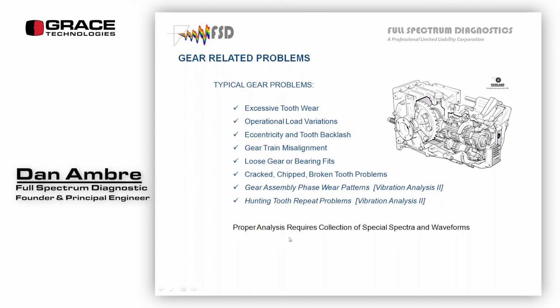All proper analysis requires collection of special spectrum and waveforms. Above and beyond your bearing defect spectrum that you're collecting, that's going to be in a certain frequency range for bearing failures, you're going to now have another set of data that's a little higher frequency, and it's going to cover that 3 times gear meshing that we talked about earlier.